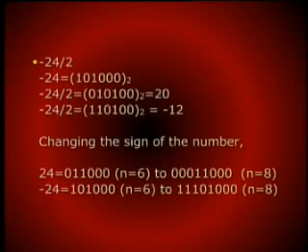Now you should note that changing the number of bits in any particular number would correspond to also copying the sign bit. If it is a positive number, copy it as 0, and if it is a negative number, then you have a sign extension bit as 1. Take a very simple example. 24 represented with 6 bits would be 0, 1, 1, 0, 0, 0.